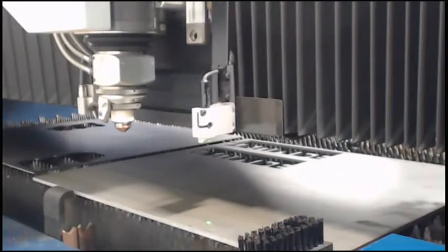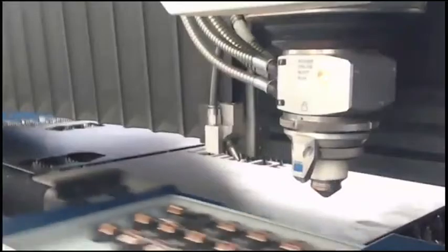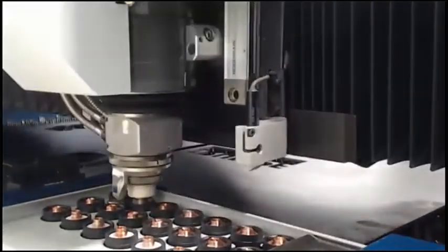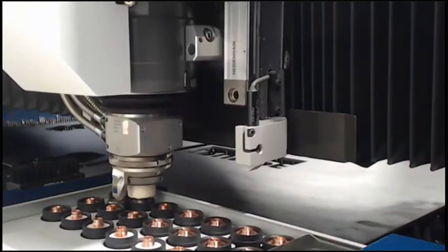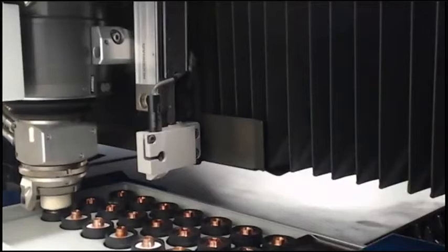So again, this is 1/4" mild steel. We're going to be using nitrogen. We're going to do another nozzle change. It's a good thing that this machine has such high dynamics with all these nozzle changes. It does them so quickly. That is certainly fortunate. Is this using active speed control also? It is. Okay. I believe it is, yes.